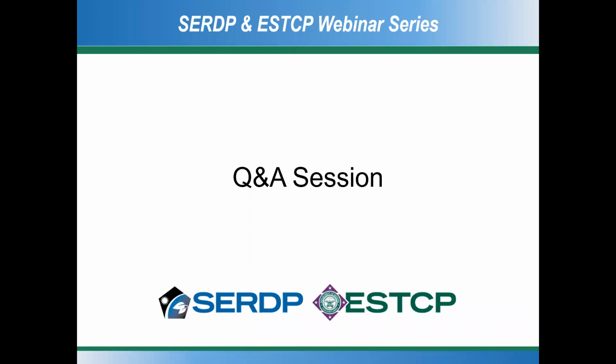Yeah, that's a good question, about the philosophical use of mass discharge in plume management. I don't mean to be vague, but I do think it depends on the site-specific situation. In some cases, a remedy objective around a specific mass discharge value may be supported. Probably in most cases that would be derived through a risk analysis, which provides a quantifiable target for performance objectives for a remedy.